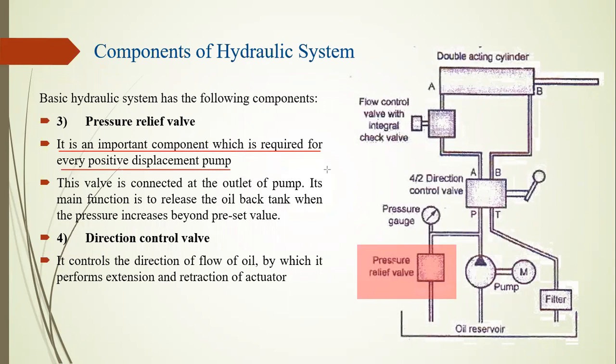the pump keeps giving higher and higher pressurized fluid inside the hydraulic circuit. It creates an over-critical pressure inside the circuit, so it can cause damage or an accident. So it is made compulsory to relieve oil from the higher pressure in the hydraulic circuit and drain it into the oil reservoir tank. That is the function of a pressure relief valve. It releases the pressure from the hydraulic circuit at over-critical pressure.